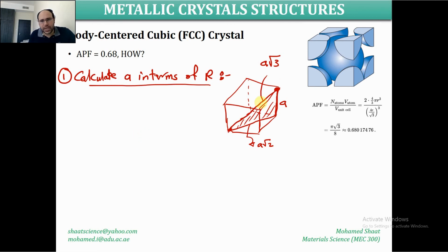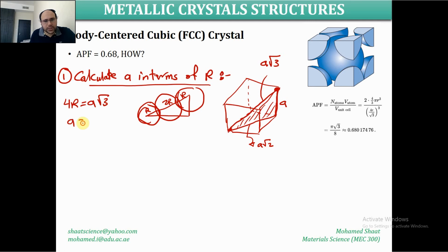Okay, anyway, we do have this A, and we agreed that over this main diagonal, if we draw this triangle one more time in this way, there should be 2 atoms, 1 atom at this corner, one atom at this corner, and there should be another atom in the middle. So this gives in total that this edge here is 2r. This distance is just 1r, 1r. So we're going to end up that 4r equals A square root of 3, which is going to give us A equals 4r over square root of 3, which is this relation that we have proved before.